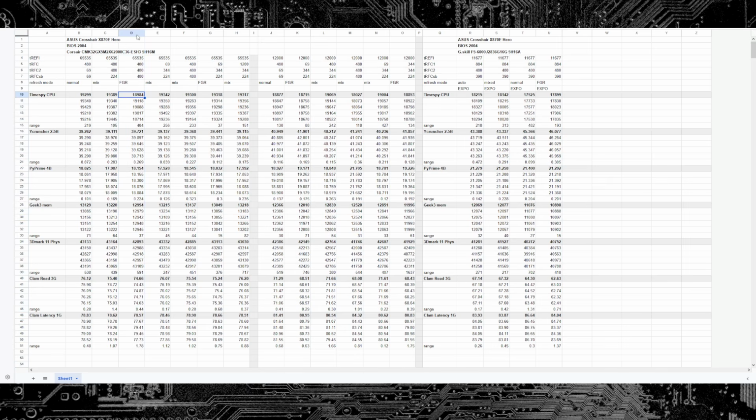if we put these next to each other, you'll notice that, actually I'll put it here, right? So it's worse than mixed mode, and it's worth noting that with mixed mode, the priority is that tRFC same bank timing. tRFC2, you can see right here, right? I tested tRFC2 equal to tRFC1 and tRFC SB low, or tRFC2 low and tRFC SB low. And I also tested mixed mode where everything is horrible, and mixed mode does a better job of that than FGR, because in FGR, your refresh interval is always being divided by 2, whereas in mixed mode, it's only sometimes being divided by 2.